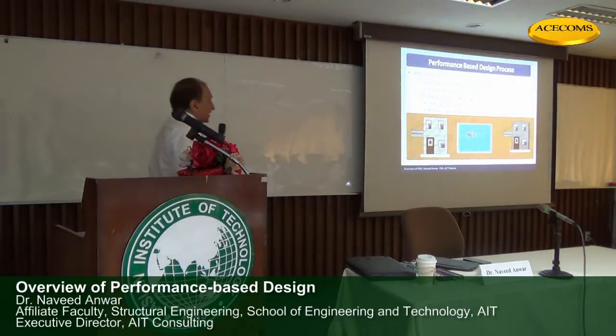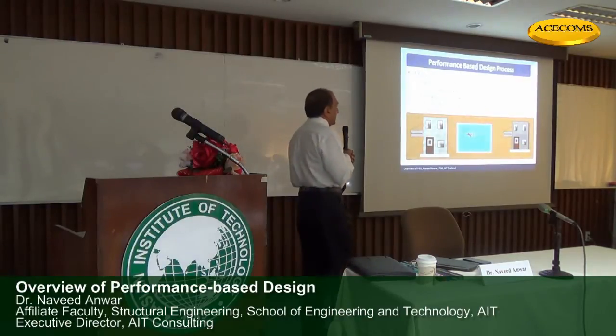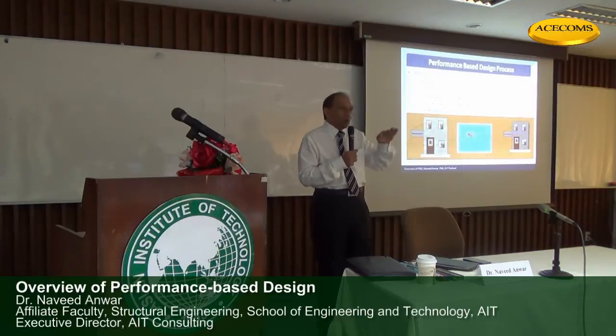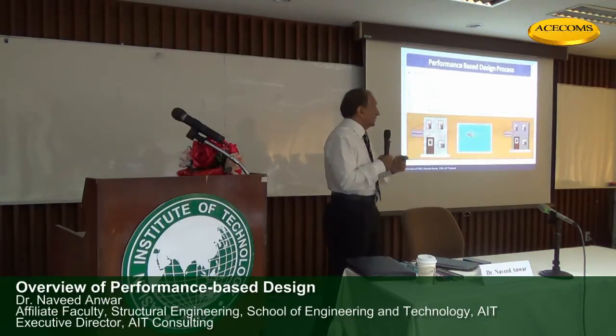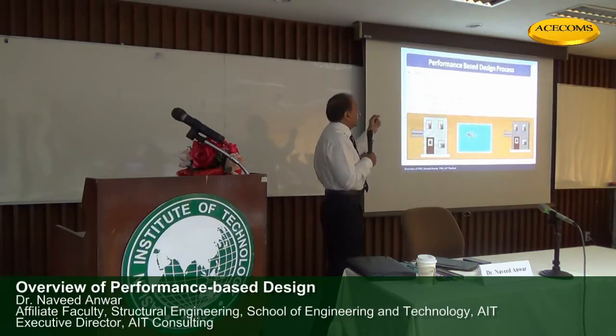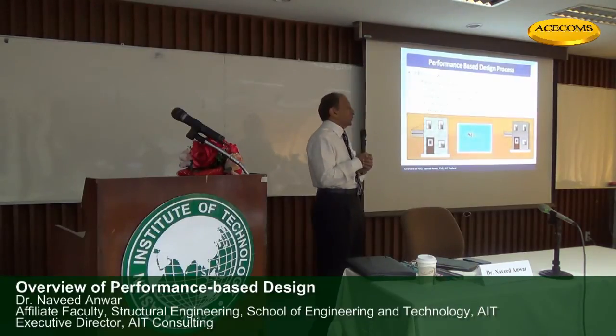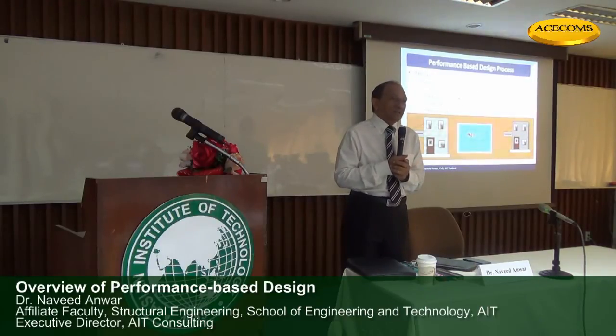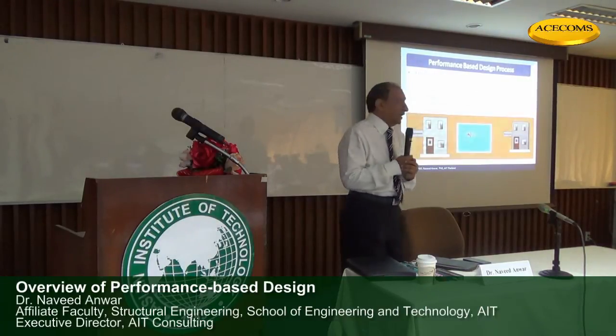So basically what we are saying is, if behavior will be essentially elastic, that means we are talking about a low level of hazard, then regular structure with short periods, for example, can be analyzed by using linear static procedures. What we are doing for code-based design is fine.